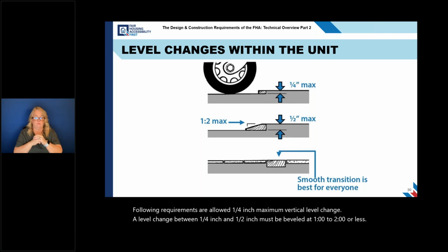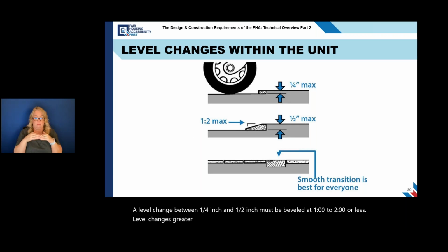Level changes greater than a 1/2 inch must be sloped at 1 to 12 or less. A smooth transition between different areas is most usable.